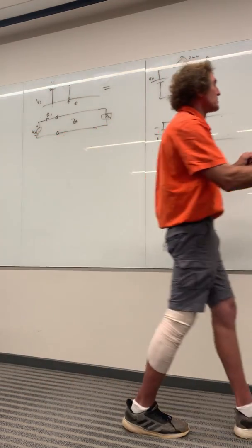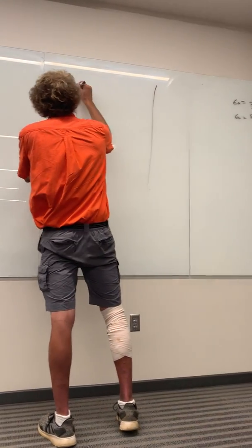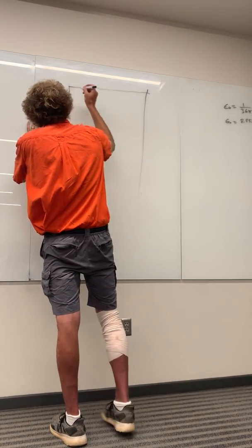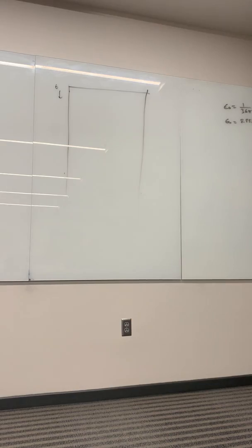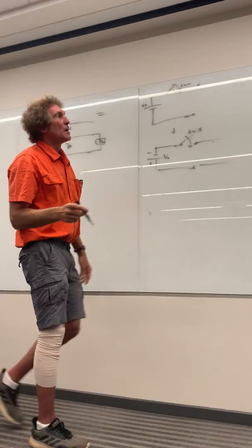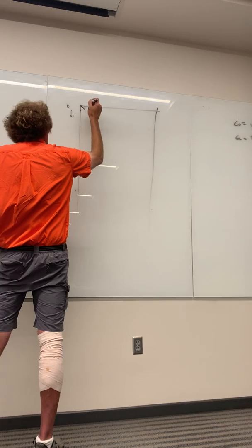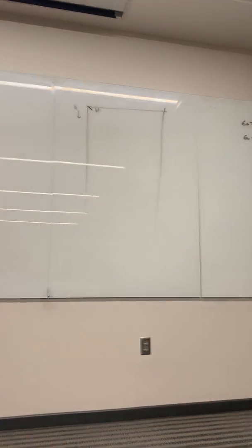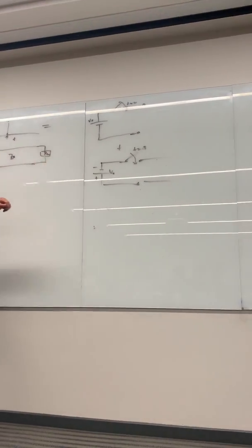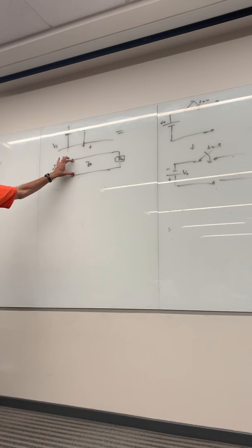So the way we do this, and he shows this on this graph, and I'm not sure how, he probably uses different colors. He takes this as time going down, and now, does he do the voltage at the load or where? Yeah, I think it's the initial voltage. Here's what you do. You start out and you get your V prime at t equals 0. And V prime, of course, would be Vs, or V naught in this case, times Z naught over Z naught plus Rs. Do y'all see that? That's the voltage just on the inside of this transmission line.